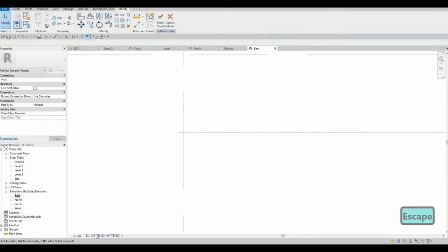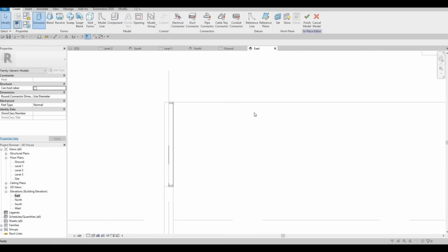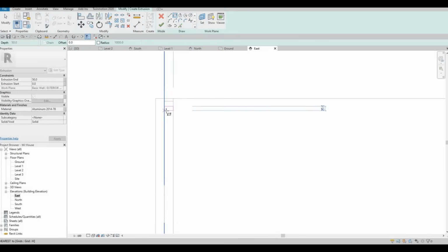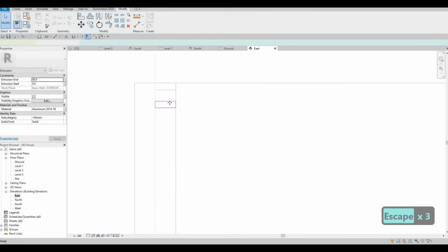and then here we cannot see it properly, but we're gonna change the wireframe, and here we're gonna create a horizontal from there. So we're still right here, click on extrusion, pick a plane, and we're gonna choose this plane. Let's choose this plane. So that's good enough. And then we're going to create something that looks like this. And then click on finish.